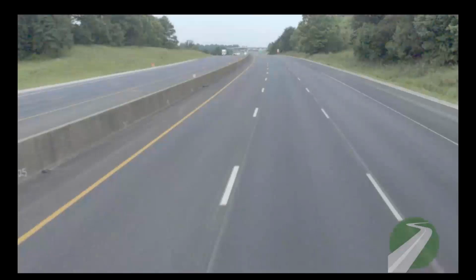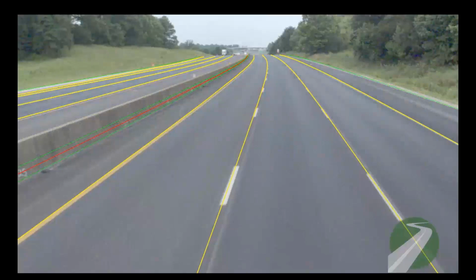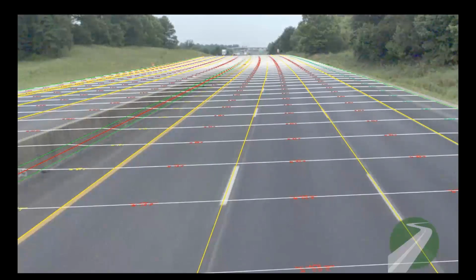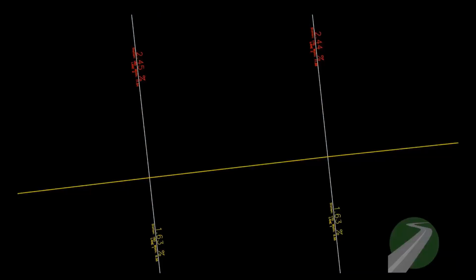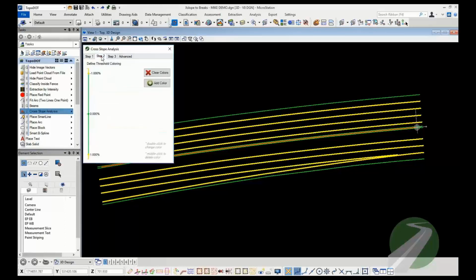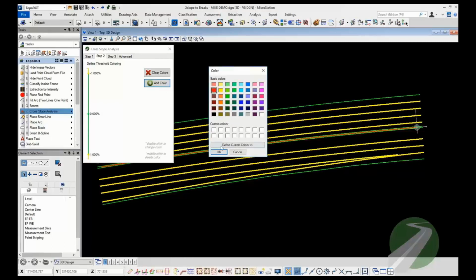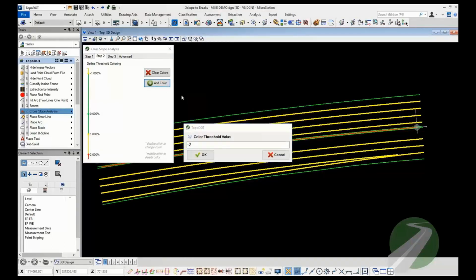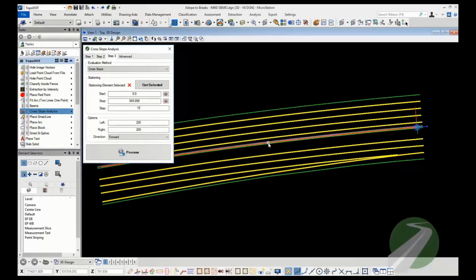Another good one is roadway geometry. Keep in mind that you could work straight off the point cloud data, but in this case, if you have the paint stripe line extracted already and maybe the barrier information, you can just quickly dart through and generate cross-sectional information, grade, and the width of these lane lines. A common application for this would be post-construction, to verify cross slopes, for example.